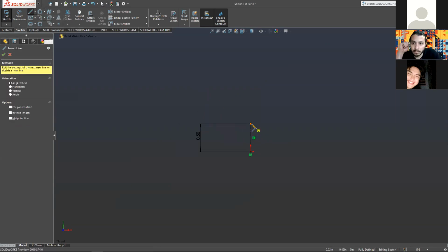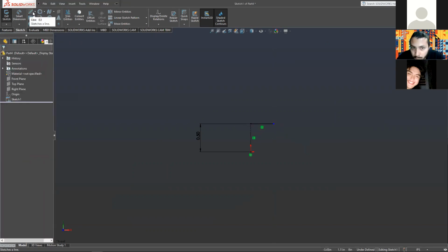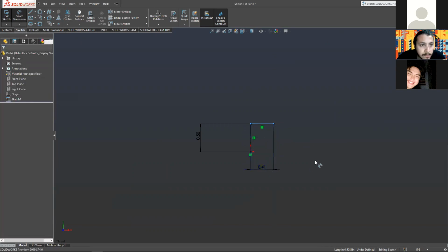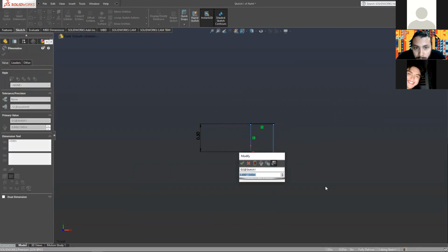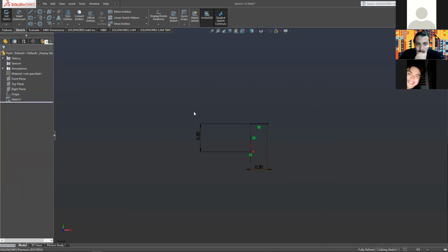So we're making a wheel and all we're doing is making the profile of it. So we'll do this. You hit another center line there, right? No, this is a regular line. Sorry, I'm not announcing what I'm doing. Regular line. Let's take it out 1/4 of an inch. Nah, a quarter is too small. Let's make it 0.3, so 3/10 of an inch. Check mark that.